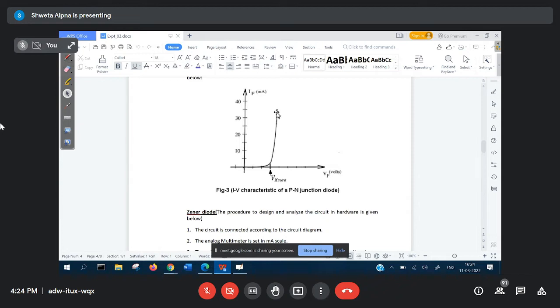The P type and N type. P type material has a lot of holes as the charge carrier. N type material present in the PN junction diode has a lot of negative charge carriers, and all these you will do in detail in the theory. And when we forward bias it, that means when we connect the positive supply to the P type of the diode and negative of the supply to the N type of the diode, the diode becomes forward biased, and the holes, being positive, are repelled by the positive supply and cross over the barrier potential, because the barrier potential has become very thin.